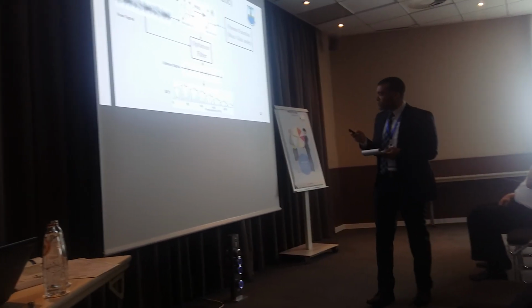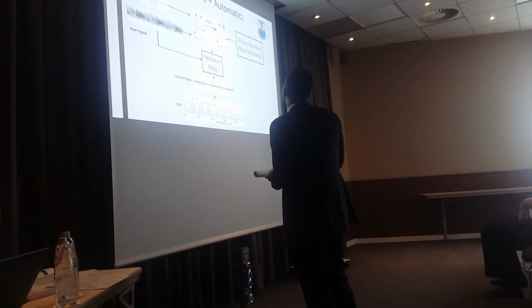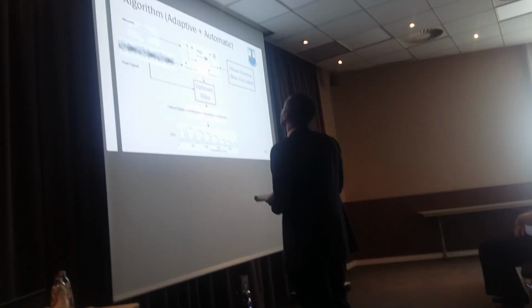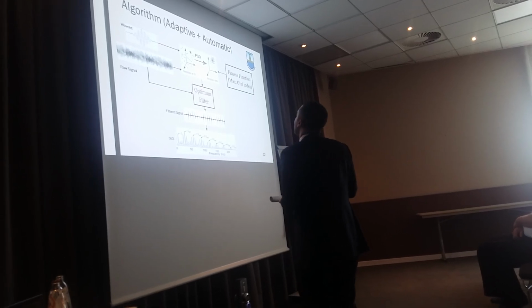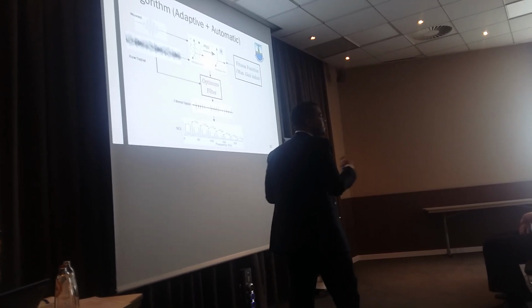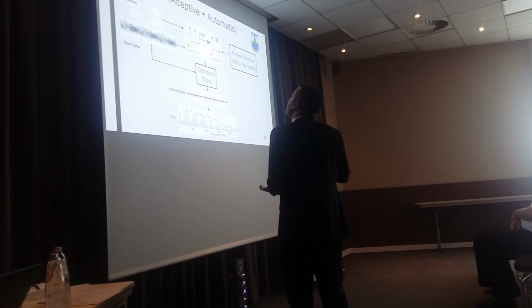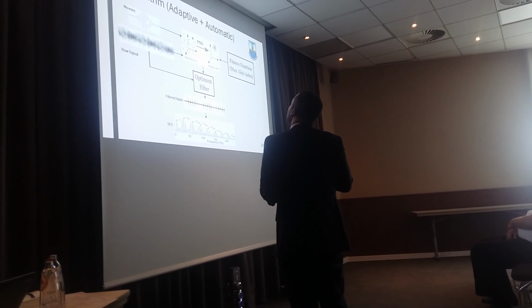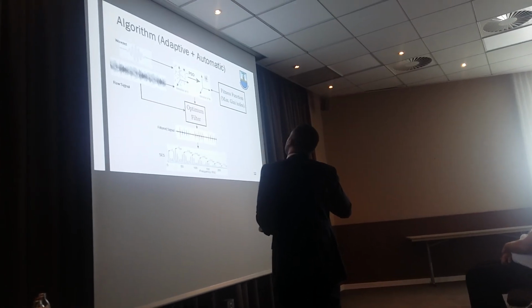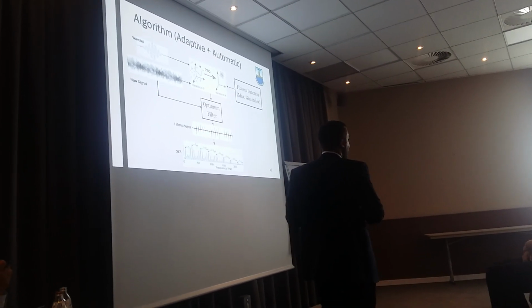The algorithm starts with feeding the raw vibration signal, along with some information about it, like the sampling frequency, the rotational speed of the shaft, and the bearing characteristic frequency of the bearing. And this is the wavelet that we want to optimize. These two things are fed to the particle swarm optimization algorithm, or the built heuristic.